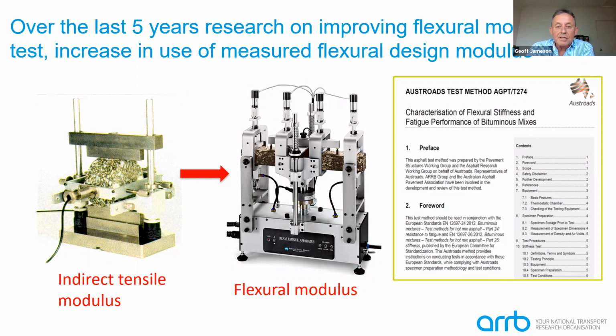And the question is, if after it does crack that layer, if you have a process there to predict the fatigue life of that layer, what is the consequence in terms of when you would rehabilitate that road? Does that cracking come through to the surface and therefore limit life in some way, or lead to additional rutting of the pavement subsequently?